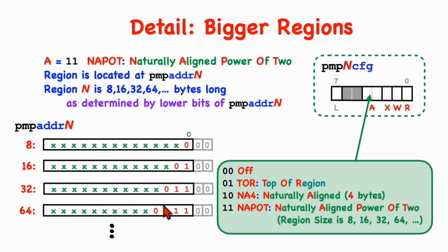And so here are some examples to illustrate how this idea works. If, for example, the first 0 is here, the physical memory protection hardware will understand that the region is to be 8 bytes in size. And with the implicit 2 zeros right here and this 0, the remaining bits give an address which is evenly divisible by 8. So it's an 8-byte aligned address.